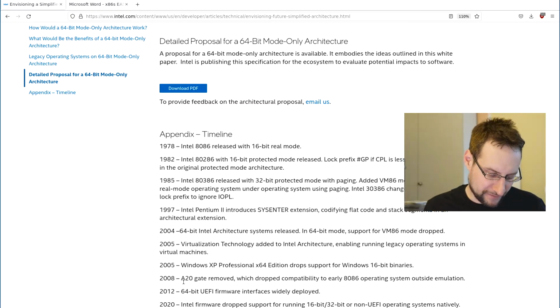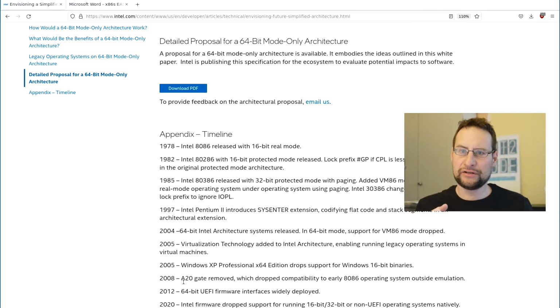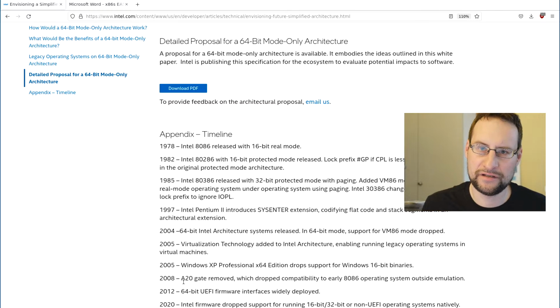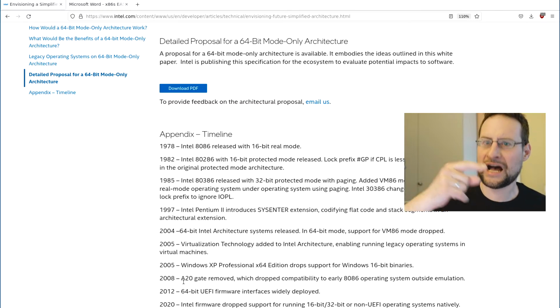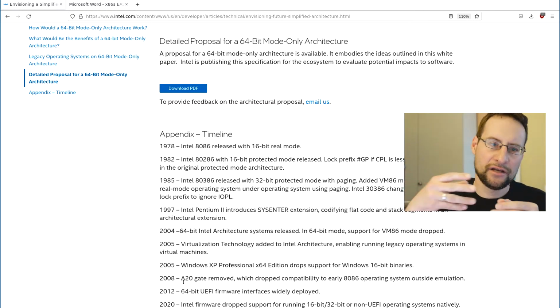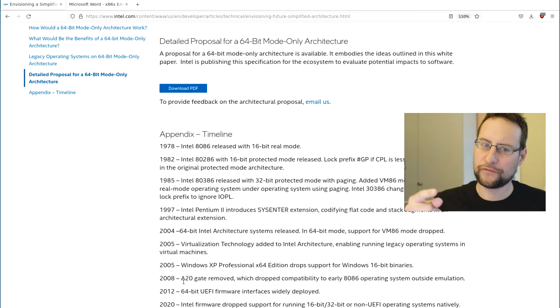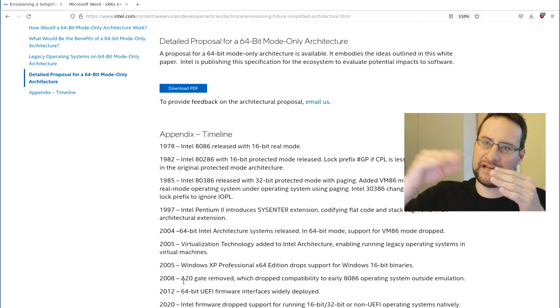So this was, by the way, for backward compatibility. If you're wondering what that was for, it is for having that line always zero, so gating the 20th address line. The thing is, on an original 8086, if you addressed the highest address, which was 1 megabyte, plus the 64K segment size, you had some overlap that was overflowing to the very beginning of the address space. So it addressed 1 megabyte and then some.